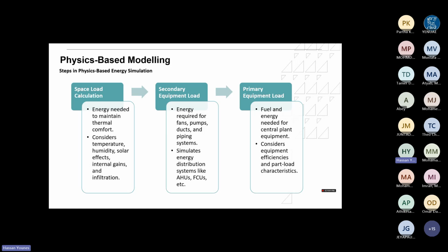So it's very, very important that we get the right information into the model. If I have a chiller from this manufacturer, I need to get a performance map, because the chiller is not like lighting. It's not just one point of entry. We need to look at the whole part load condition. What would happen if the chiller was running at 30% load and the outdoor temperature is 45 degrees C and it's an air-cooled chiller? What is that kilowatt per ton? What is that COP?